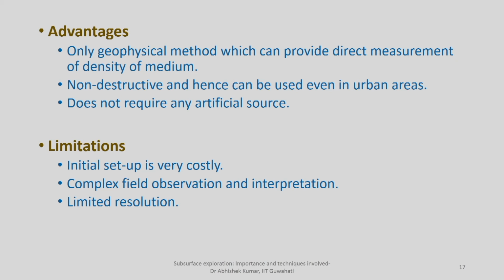Second advantage here, as you might be seeing, we have a small instrument, we go to the site and measure it. So, we do not require any kind of external or artificial source for generating any kind of resistance, because of which the soil or the subsurface medium is going to offer resistance, and it is non-destructive. You are simply measuring the gravity pull at the ground surface. So, it is more suitable for urban areas where you are required to do some test to understand subsurface medium characteristics without disturbing or causing much noise.